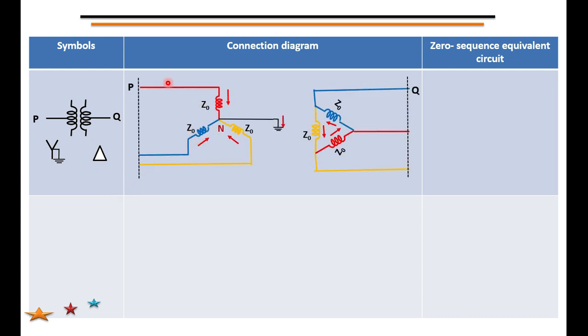It is star connected. The primary is star connected and grounded, and the secondary is delta connected. Then we have to look into what is the path for the zero sequence current, that is, the current, since the primary is grounded. Suppose the current is entering here. I am explaining only for R phase. It is similar for the B and C phases also.